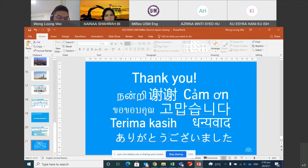So the first thing to see whether a grinding aid is good or not is that once you use a grinding aid, you can increase the capacity of your production. For example, if the grinding process without a grinding aid is only running at 100 ton per hour, once you use a grinding aid, you can increase your capacity by 10 or 20%. So this is an efficient grinding aid.